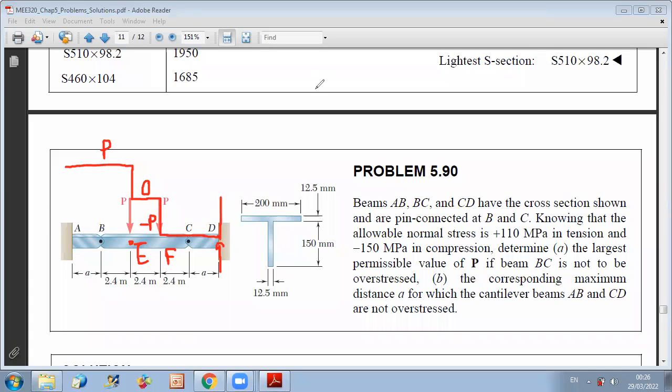Okay. Also a note: whenever you have symmetrical beams with symmetrical supports and symmetrical load, the shear will be anti-symmetrical, while the bending moment will be symmetrical, and you can observe this from your diagram. Why do you have this?